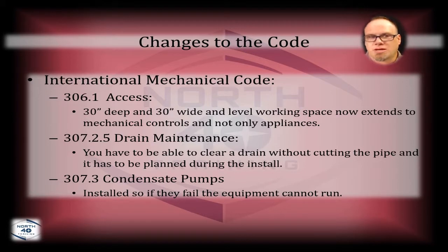Vinyl tube, I get a lot of guys that ask me about vinyl tube. Can I use vinyl tube for my drain? It doesn't say anything about you not being able to use vinyl tube. People have just gone to the PVC on the 3/4 side, because vinyl tube, once you get over that 5/8 vinyl, which used to be incredibly popular for most of the early 2000s, that stuff is easy to maneuver and guide around stuff, and it's small enough that if you run it under a carpet in a basement, it doesn't create much of a tripping hazard.